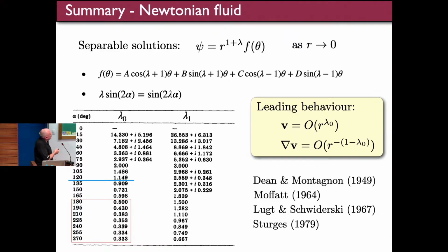So in other words, the region of interest for the extruded swell is between a separation angle of between 180 and 270, right? That's the range we're interested in. So our velocity gradients are going to be very singular when you differentiate this twice. So these exponents go negative for the velocity field and the velocity gradient. That in turn induces a singularity in the viscoelastic stress as well.